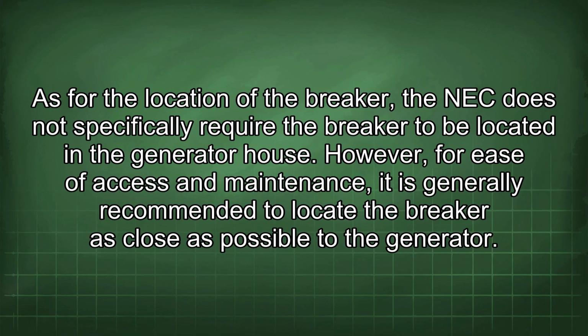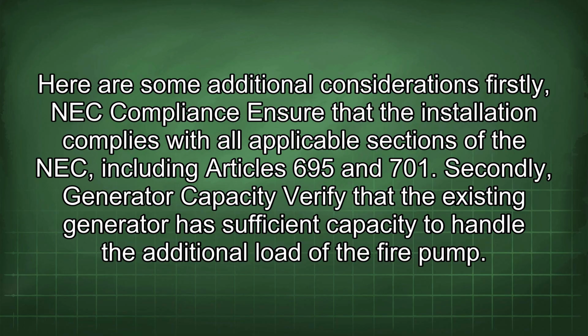As for the location of the breaker, the NEC does not specifically require the breaker to be located in the generator house. However, for ease of access and maintenance, it is generally recommended to locate the breaker as close as possible to the generator. Here are some additional considerations.